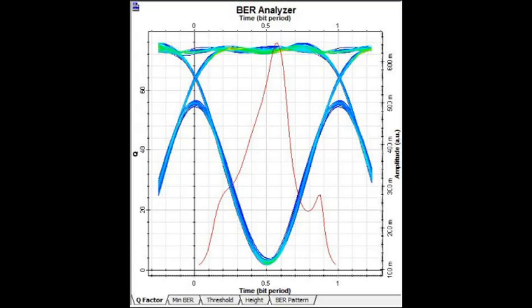For the optical circuit with modulator, the wavelength of 780 nanometer and power of 100 milliwatt and 25 terahertz of frequency deviation is set. By using the earlier value of attenuation with 10 dB per kilometer, the BER analyzer shows the Q factor value of 79.145, minimum BER value of 0 and 0.918894 value of eye height at the range of 4 meter.